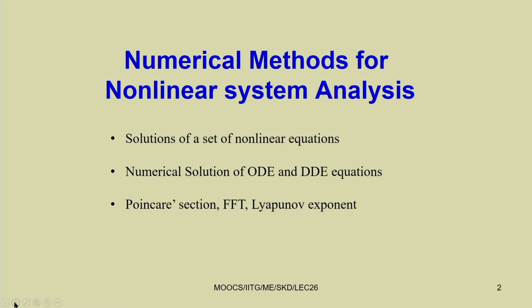For example, for finding the characteristic constants or solving the characteristic equation to know the frequency function, we have to solve a single equation. And sometimes to find the response we have to solve a set of nonlinear equations also. You have seen a set of nonlinear equations in case of the reduced equation we have derived in the method of multiple scales or in other methods also.